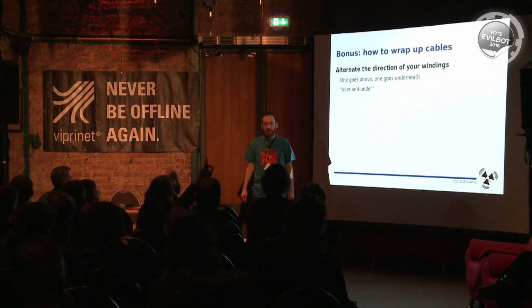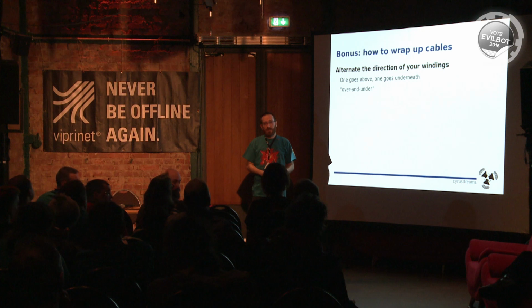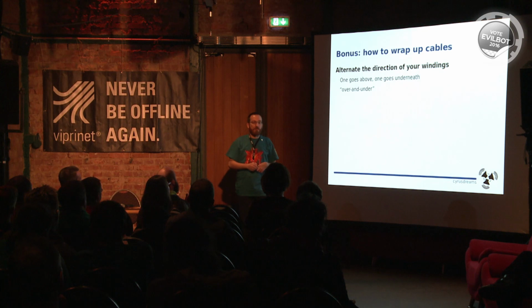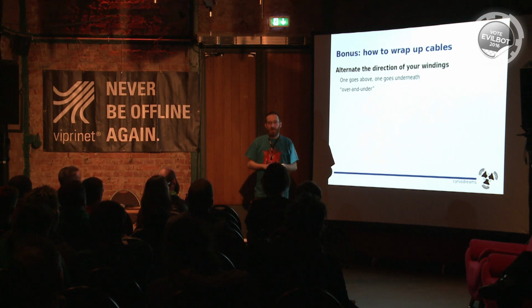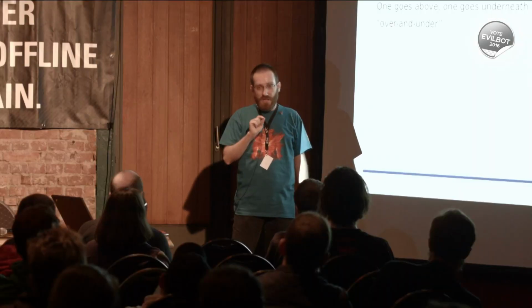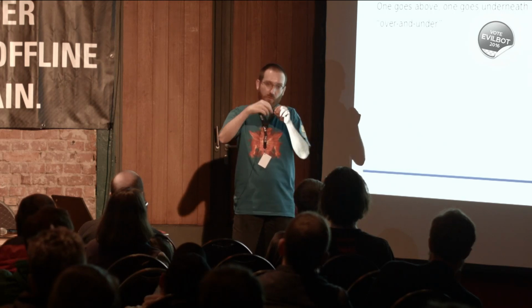Yes? What was the technical difference between the audio switch cables and similar looking cables for video? The question was, what is the difference between the RCA audio and RCA video? From the connector side, they are identical. The difference is for video you must use a coaxial cable, and they start getting controlled impedance. Even if the audio cables most of the time are also built coaxially.